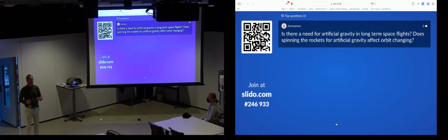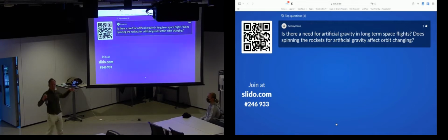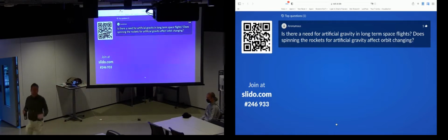just like a gyroscope, when you have a gyroscope, you have to push in different ways. But that's relatively well known. The real problem with spinning a spacecraft up is if your radius is too small, you get horrible, horrible tidal effects. So what happens is, if your feet are on the floor, which is the outside, and your head's sticking to the inside, the acceleration of your feet is very different from your head. And it's not exactly nice. If you lie in the curvature of it, it's not so bad.